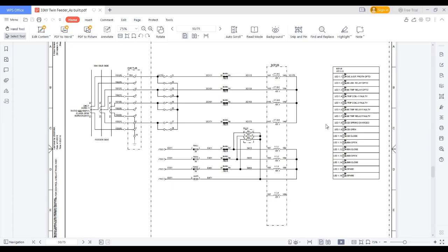And then we are also looking into the control indications, followed by master trip circuits, LBB trip circuit, and breaker closing and tripping circuits, breaker pre and post close supervision, trip circuit supervision circuit, and again the output indications from the isolators and the switches, and the contact multiplication relays.